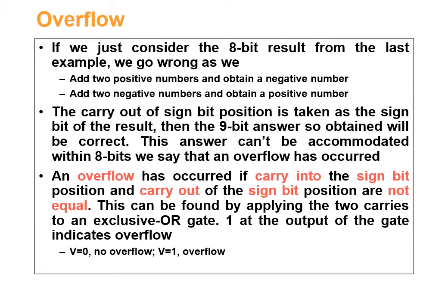For this method to work correctly, the 2's complement of a negative number must be computed by taking the 1's complement and adding 1. This takes care of the condition when the maximum negative number is complemented.